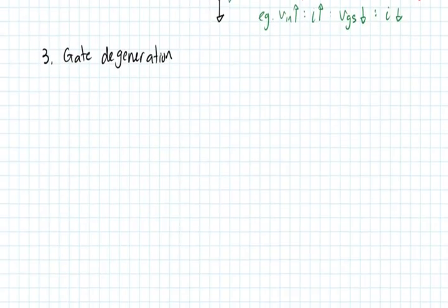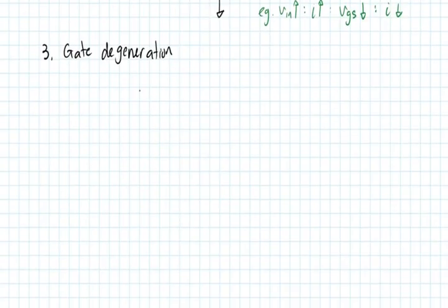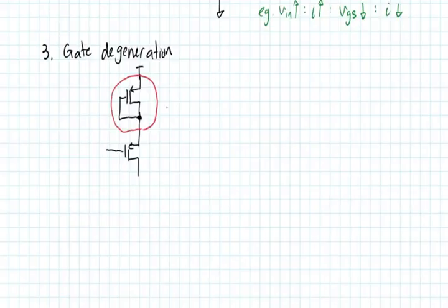Okay, so let's imagine that we transition to a PMOS input for the purposes of this example. So this is our PMOS device. Let's say we apply some sort of source degeneration to it as well. Again, this is a PMOS, so I'm going to use a source degenerated active transistor instead of a resistor. So you can think of this as some sort of diode that's acting as some sort of resistance.